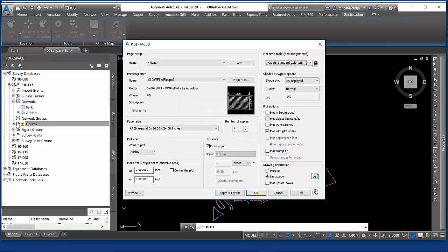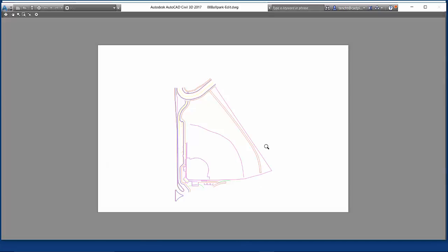The framework obviously supports both STB and CTB these days, so both are there. And this is the way that I control what my finished line weights and so on would be for my client output, rather than messing with all the layers and the styles in Civil 3D to get that stuff right. Once again, we could preview that one.